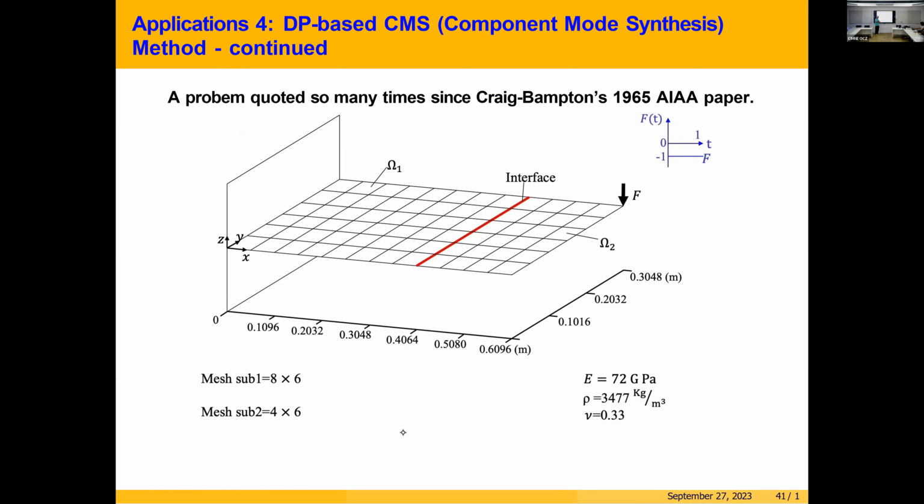This really is an innovative component mode synthesis theory, basically. This is the thing that Craig and Bampton used in their famous 1965 paper on component mode synthesis, which is implemented in all conceivable finite element codes. Okay, that is the Craig-Bampton method.